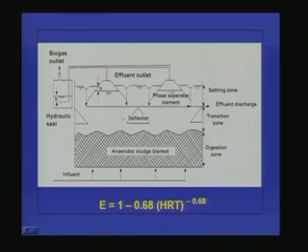So once it comes here, if it hits like here, what will happen? The gas present in the microbial flock will get separated from the flock. Once the gas bubble gets separated from the flock, the apparent specific gravity or apparent density of the microbial flock will increase. So definitely the settling velocity will increase. So the microbial mass will go out like this, and whatever gas bubbles are released will come and get collected here.